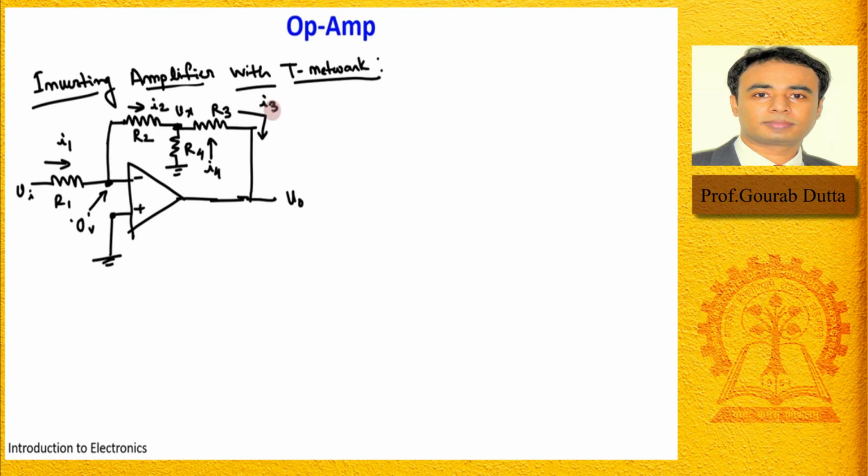Fine. So remember, here we are considering the ideal op amp where the open loop gain is infinite, and that's how we have used the virtual ground concept, and we have seen that this potential is at 0, right? Okay. Then what will be this I1? I1 is nothing but V1 by R1, right? And this is the same as this I2.